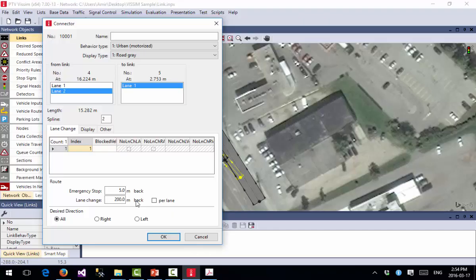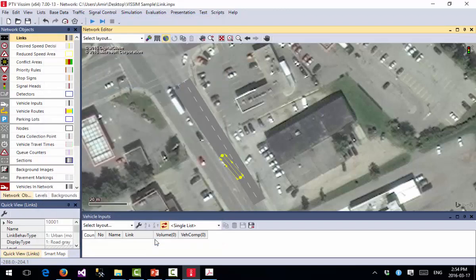Is it possible to copy and paste this link? Yes, sure. Normally what I do, just to give you a hint, is that you see this is a 4-lane intersection, which is very common. You can draw the links here, but normally I do one intersection, keep it, and copy paste the 2 other ones. Normally the geometries are similar. When you do many simulations, you will have some typical connections and intersections, for example 1 lane, normally 2 lanes, and this geometry is very simple. Whenever I want to put it here, I will just do some fine tunings and small adjustments.